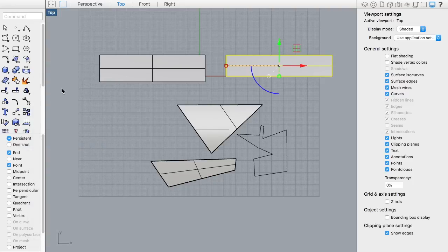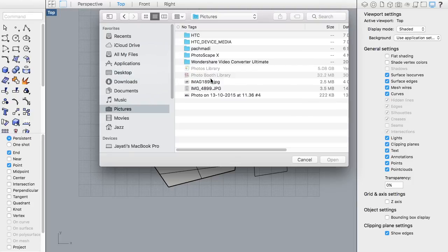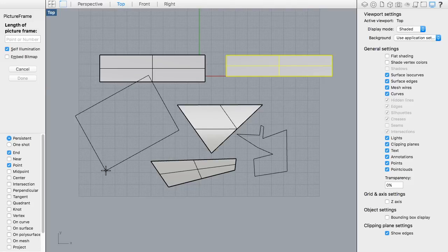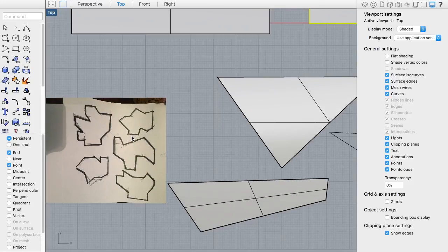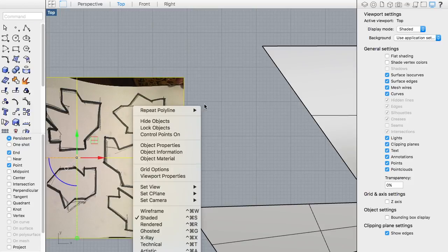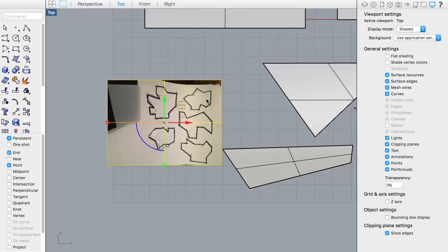If you're making a picture frame, basically if you want to import a picture into the software, that you've sketched a concept out and you kind of want to import it in. So maybe I will import this drawing. Imported this drawing and now I can kind of trace it out, right? And when you click on this and it kind of pops up again and again, you can just lock this, right? To lock this, rather than trying to find the tool, just type in lock, right?